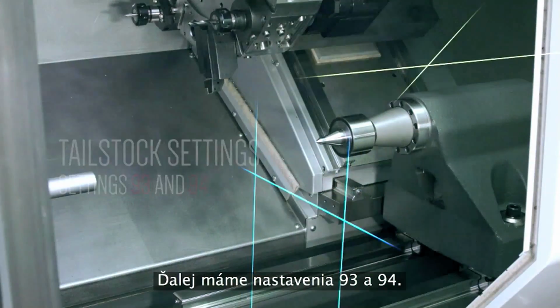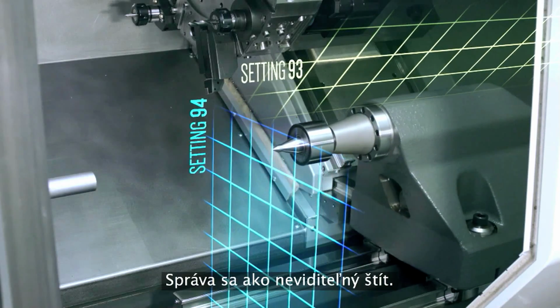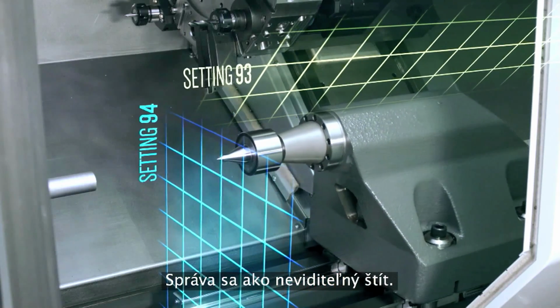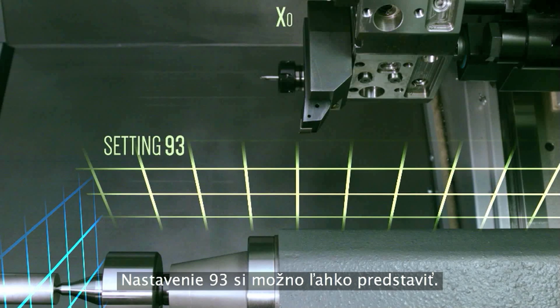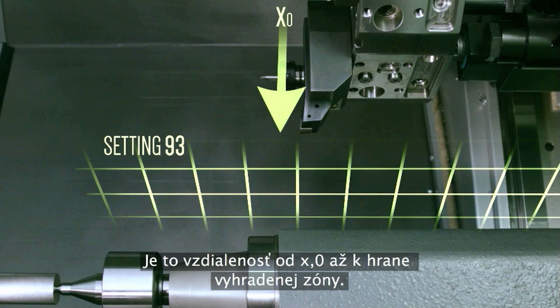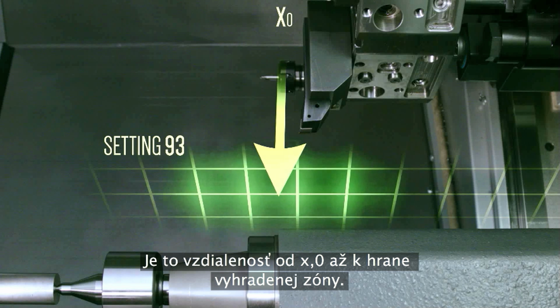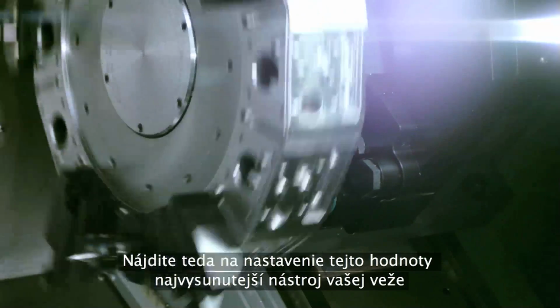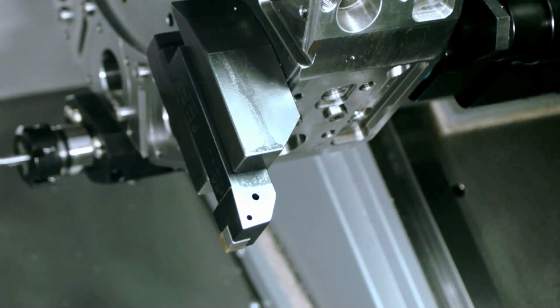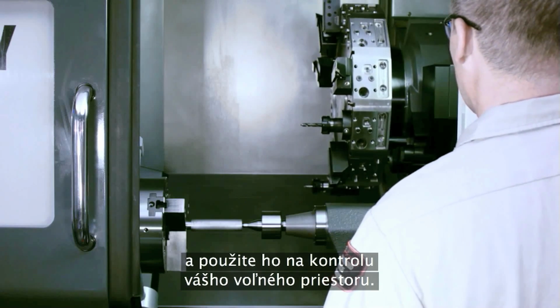Next, we've got settings 93 and 94. These define a region around the tailstock, which acts like an invisible shield. This shielded zone moves with the tailstock. Setting 93 is easy to visualize. It's the distance from X0 down to the edge of the restricted zone. So to set this value, find the most extended tool on your turret and use that to check your clearance.